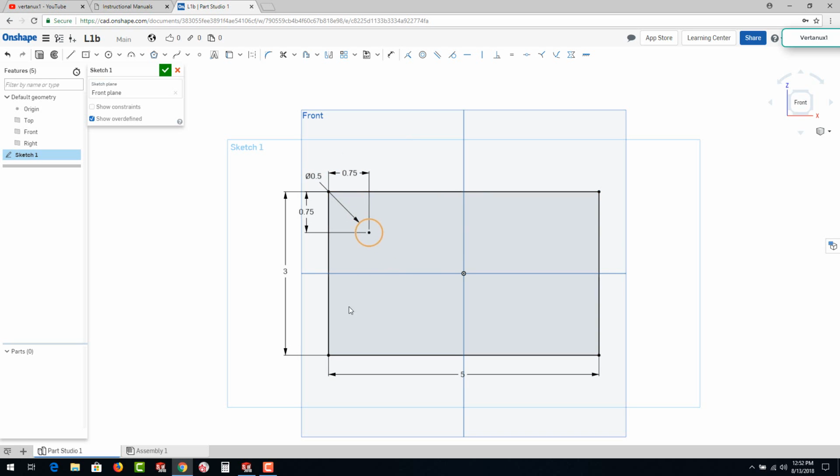So what we're going to do, I would like you to go ahead and do all of those normally. Otherwise, you could actually do the mirror tool here. And so for the mirror, we could draw a line and change them to construction geometry. So I'm going to click here and here, hit escape. Oops, I didn't quite finish that one, but I'm going to right click on this line and turn it to construction.